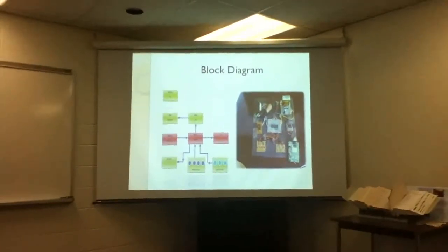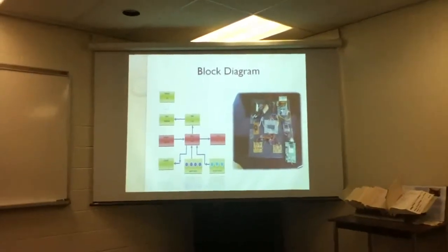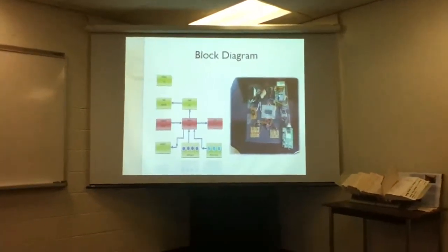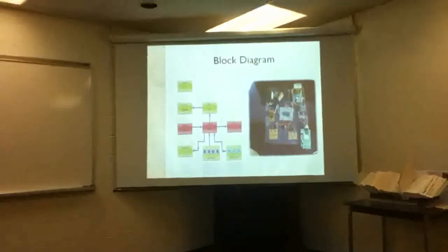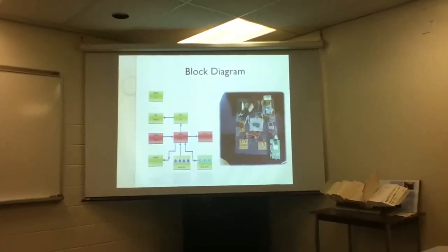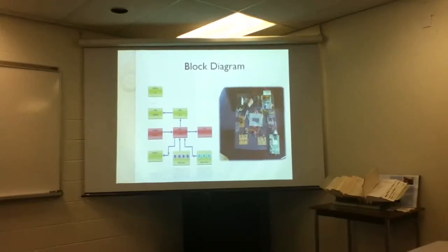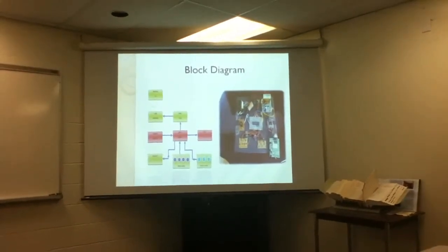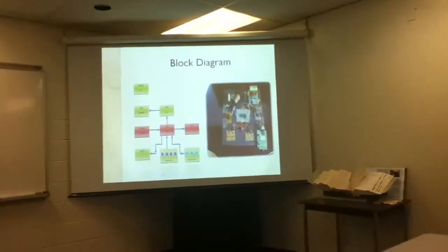And then we have a crystal oscillator on the same circuit, which is used to communicate between the microcontroller and the mobile phone, and which is supported with two capacitors. Then we have used a 16-pin LCD, for which pin number 1 and pin number 16 are ground, and 2 pins have been used for the contrast.